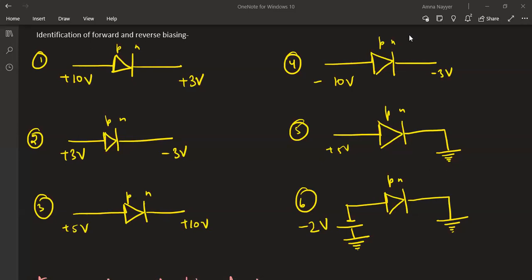Not positive. P type does not mean positive. It's just the name given. Though you can relate it with positive holes, do not have positive charge in mind. Otherwise, whenever electrons are in minority, or if electrons are more in P type somewhere, it will become confusing for you.